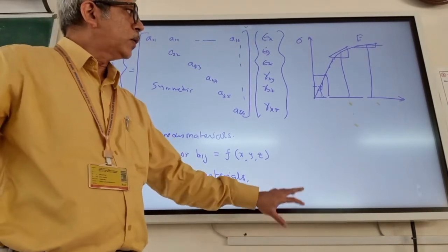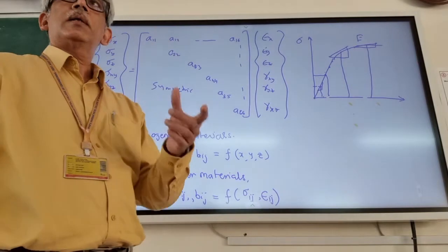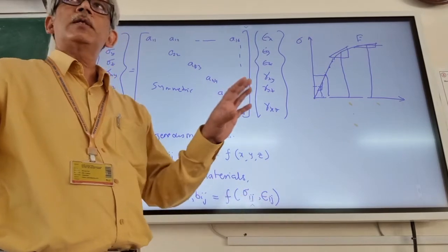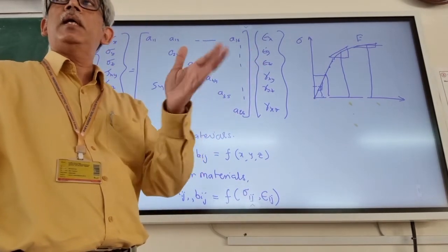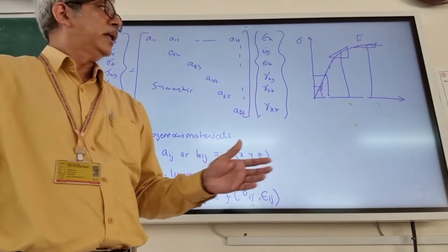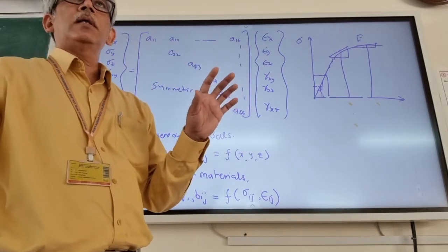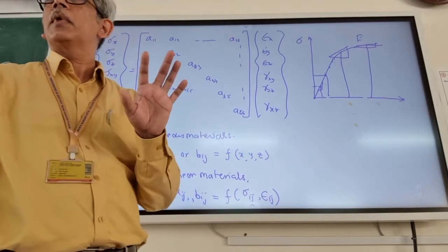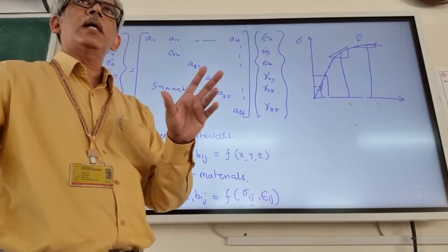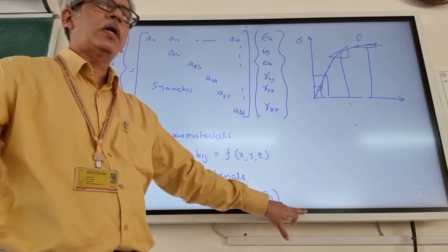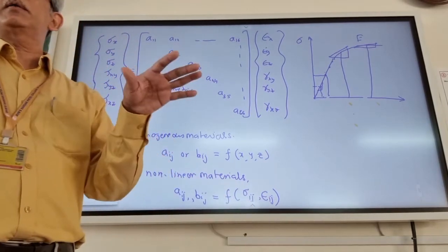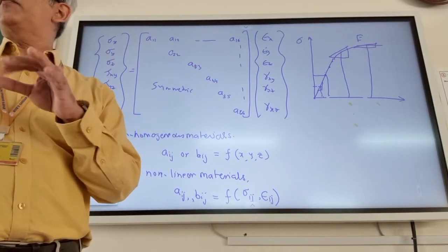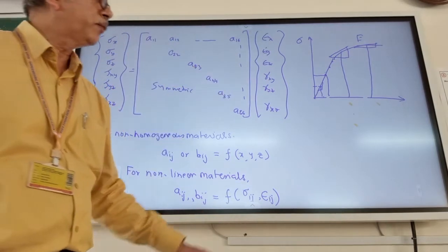So now we will look into some expressions which are commonly used in solid mechanics. Those are known as Lamé coefficients. For isotropic material, instead of talking about E and nu or E and G, we talk in terms of what is called a Lamé coefficient. We'll just have introductory knowledge about what these Lamé coefficients are and how they can be used for calculation, because in some of the higher solid mechanics books you may encounter material properties defined in terms of Lamé coefficients. So that is what we will look into.